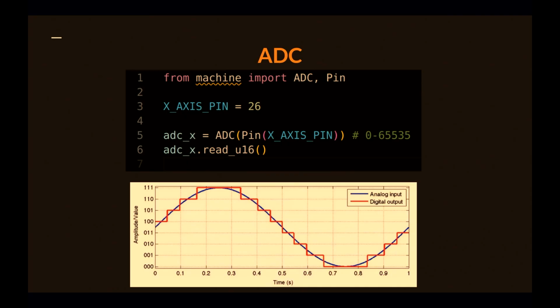The next thing that we will use today is ADC, analog digital conversion. So the trick is that we live in a physical world and we have continuous signals, but microcontrollers, they work with numbers, and let's imagine that we have a temperature sensor that generates the temperature in that room, and depending on the temperature, we will have different voltage level. And ADC does exactly for us this conversion from analog value to digital value.